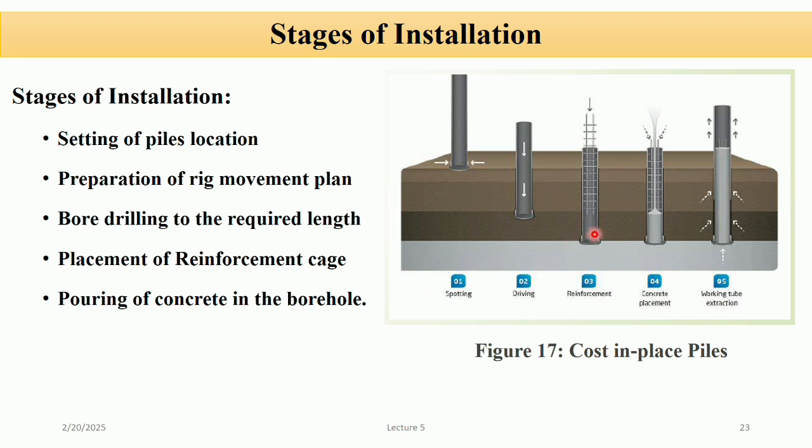Pouring of concrete in the borehole. And the last, first ensure the borehole is clean and free from debris before pouring. Then pour concrete into the borehole, typically using a tremie pipe to prevent segregation and ensure uniform placement. So these are the stages of installation.